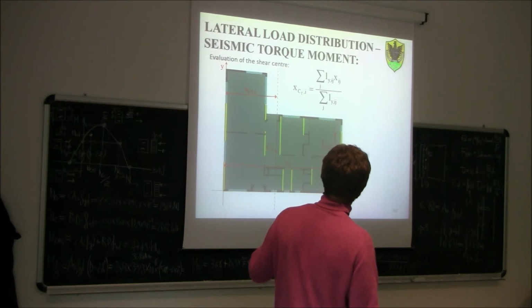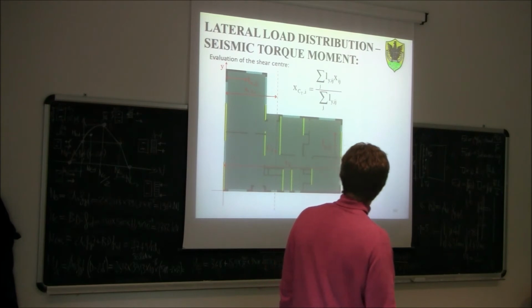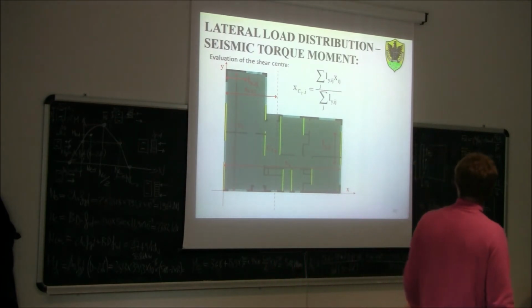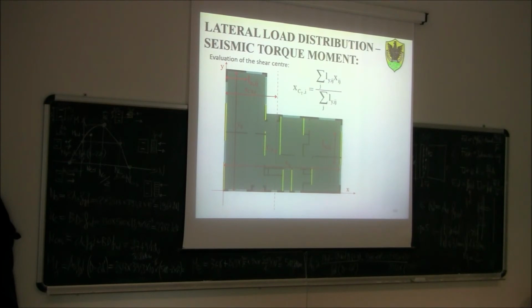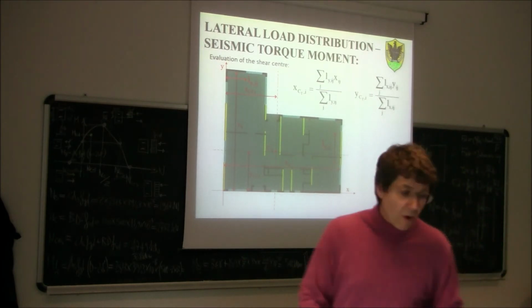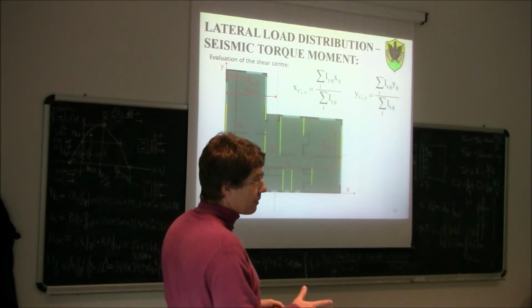Of course, in this way I can calculate the distance of the center of stiffness parallel to X, and then also the distance of the center of stiffness parallel to Y. In this case, I consider not only the walls which are parallel to Y, but also the walls that are parallel to X. We just need to keep in mind that each of these walls will provide a restraint only for displacement parallel to the plane.